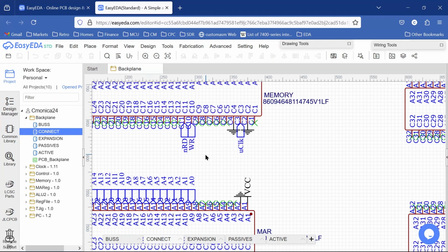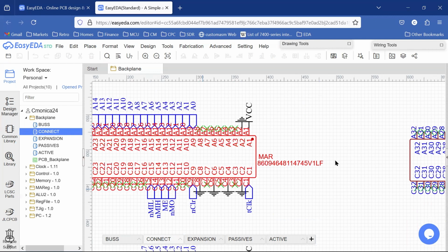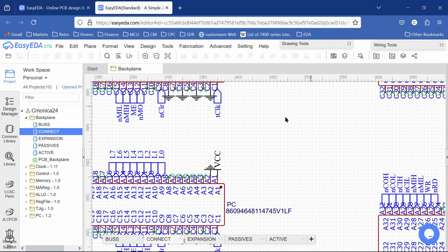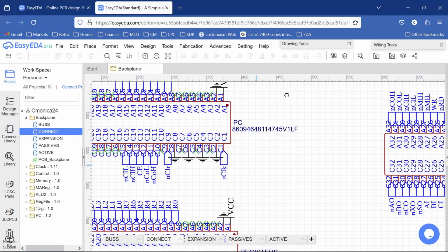It's not a big deal. It's not causing us a problem. We're not having any wiring issues per se, but it just means that on some of the cards, C10 is a ground, and on some of the cards, C10 is no connection here. Oops. C10 is a signal here, and whoops, rather, C10 is no connection here.